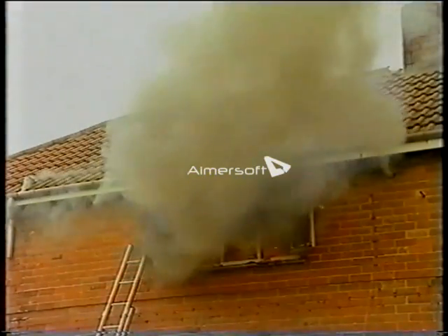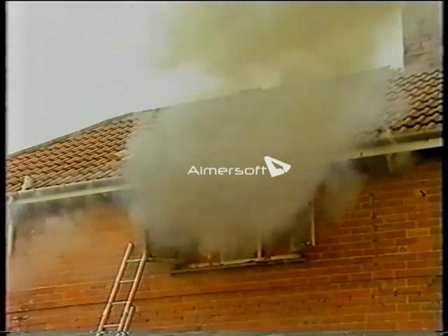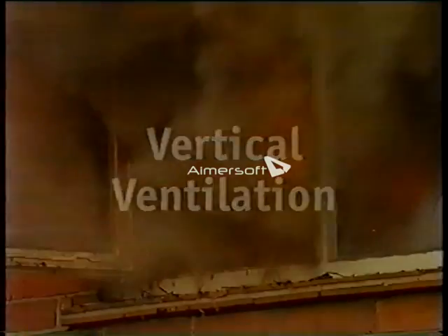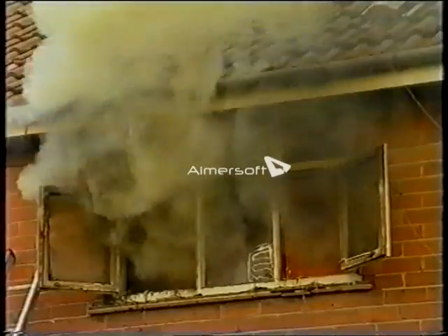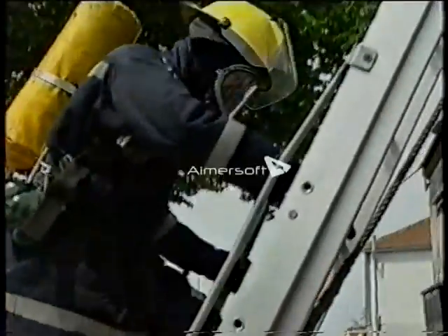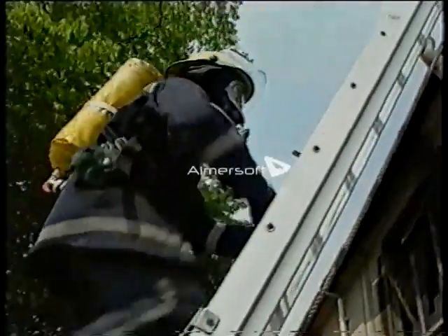The first stage in venting a room is to make an outlet vent. On the route to the vent, hot gases will always present a risk of fire spread, so this distance should be kept as short as possible. Hot gases and smoke are buoyant and will rise. This means that the dangerous byproducts of combustion will be best controlled by venting as close to the fire and as high up as possible.